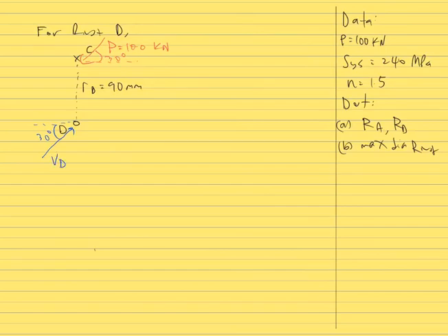So this is VD. And then at centroid we have applied moment, which is MP acting on clockwise. At rivet D we have resisting moment, which is MD equal to FTD times with RD. So we can assume the direction of tangential force for rivet D is on the right side. So this is our FTD perpendicular with the RD.